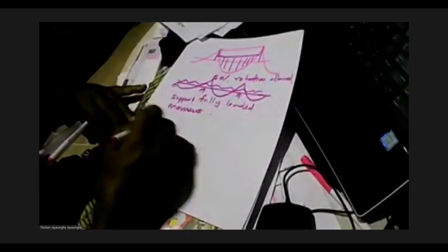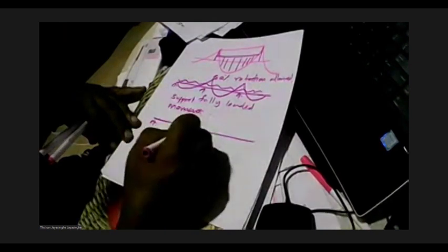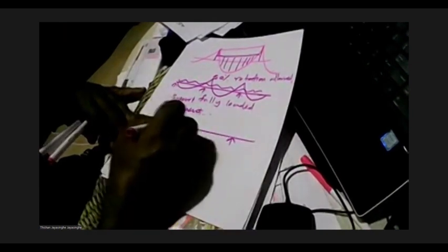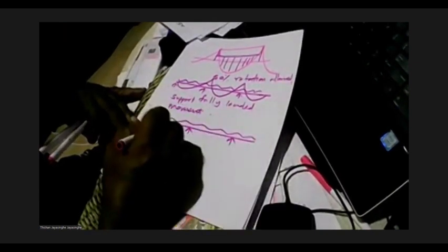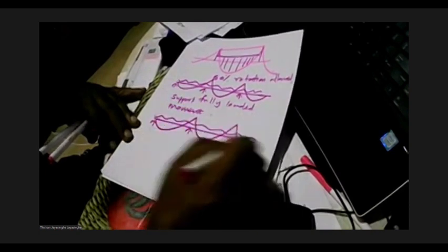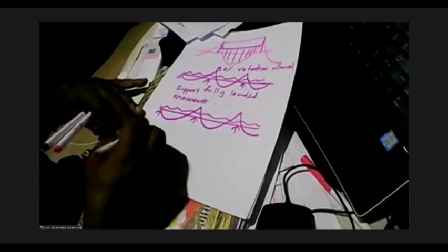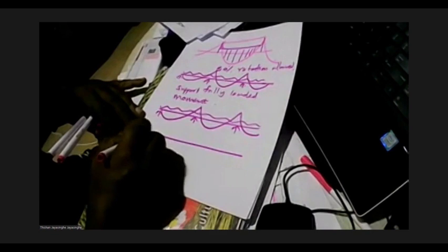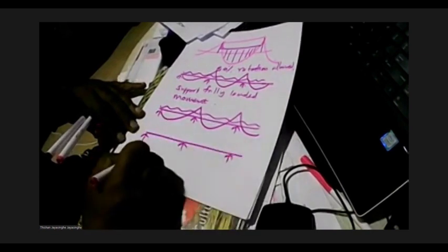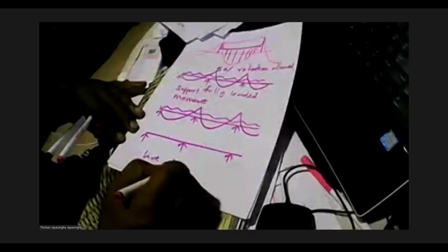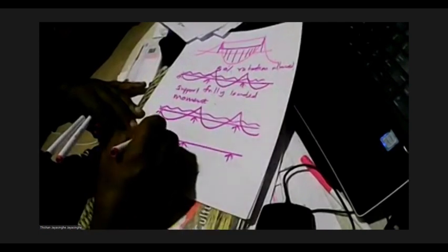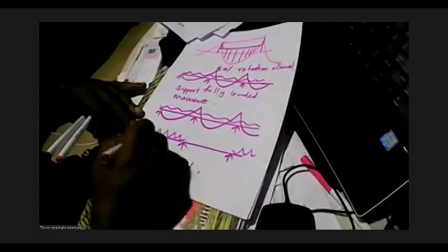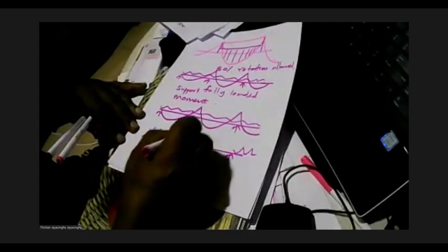For the span moment, for dead load, all these will act simultaneously. So again, you get this. For live load, we are going for pattern loading. So you get a different diagram.